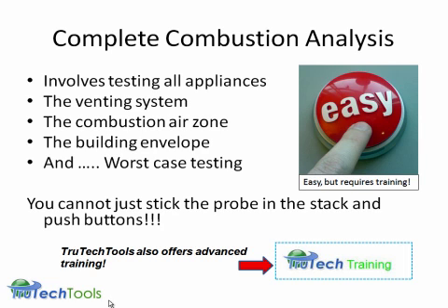Complete combustion analysis involves testing all the appliances, the venting system, the combustion air zone, the building envelope, and worst case testing. Now, what's important to realize is you can't just stick the probe in the stack and push buttons. There's no easy button. It requires some training. And we do have some advanced training in combustion if you're interested in that later.